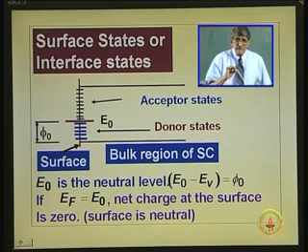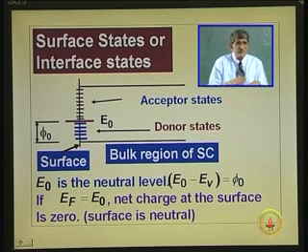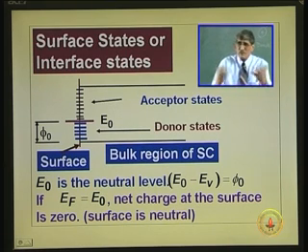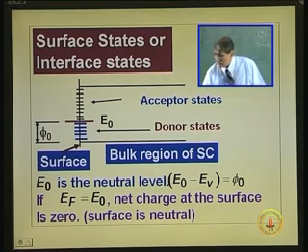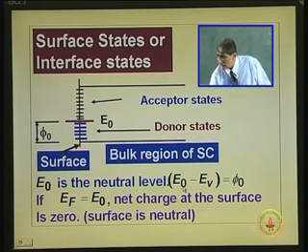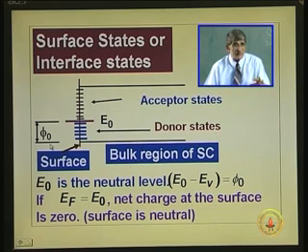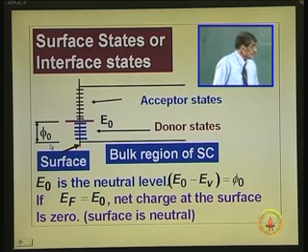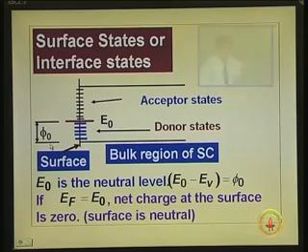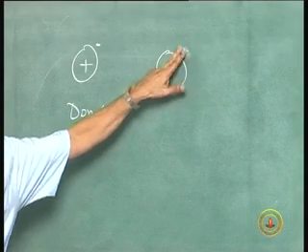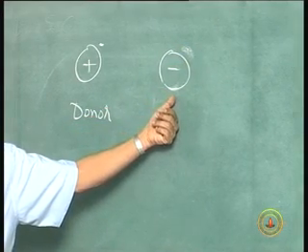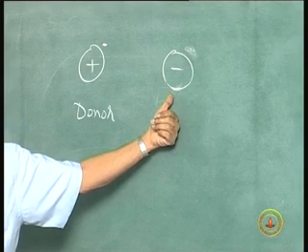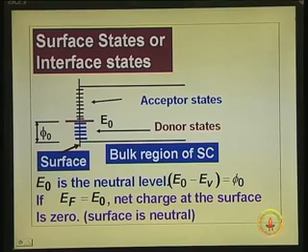So, if the Fermi level, okay, is that clear enough? It is very simple to understand, electron occupying, not occupying. So, if it is occupied below this donor level, it is neutral. The acceptor level, if it is not occupied by an electron, it is neutral. If I remove that, if it is occupied, it is negative. If it is not occupied, it is neutral.